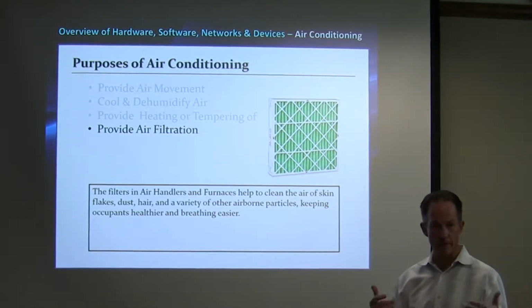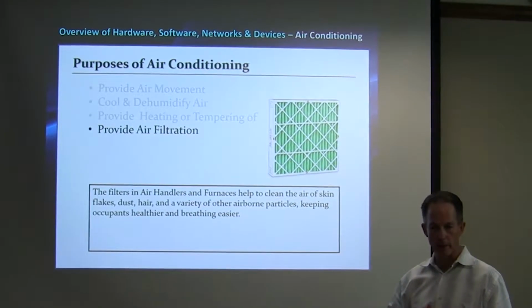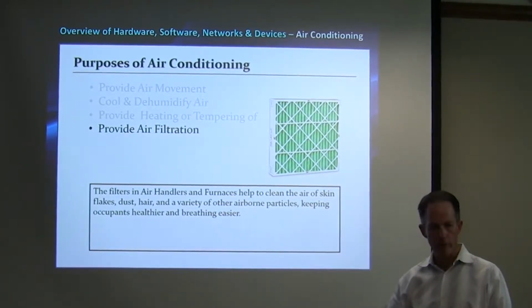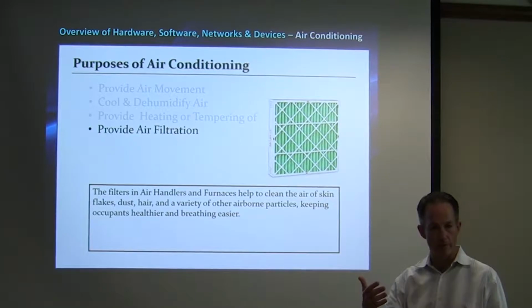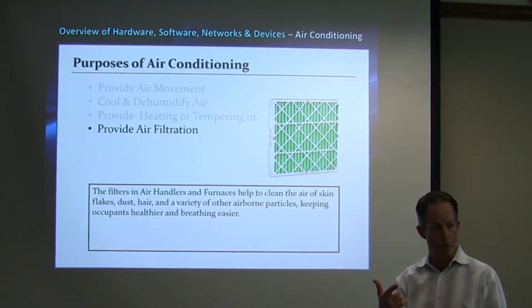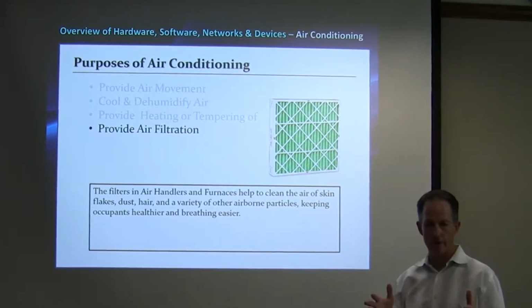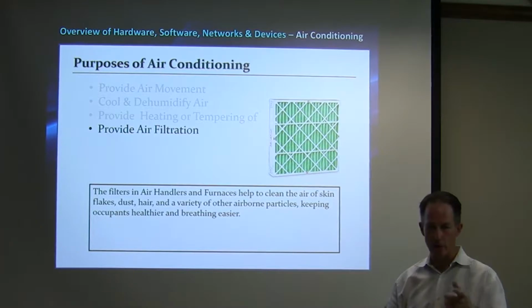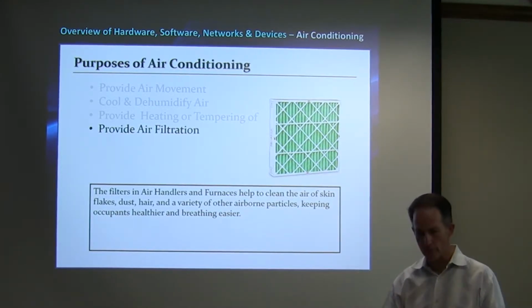We try to mix our air, filter it after that, so that we get both filtered and clean it up as best we can. What are the ratings on our filters? We're MERV 8 on our pre-filters, MERV 13 on our final filters. We have 14s, I think, in the Museum of Art. So a few other places maybe.